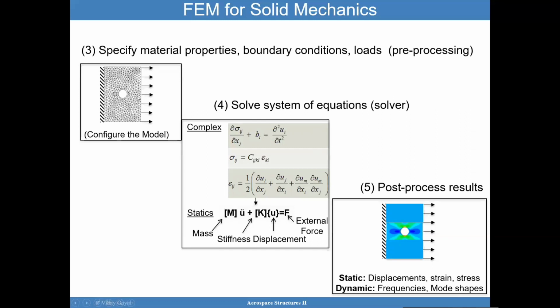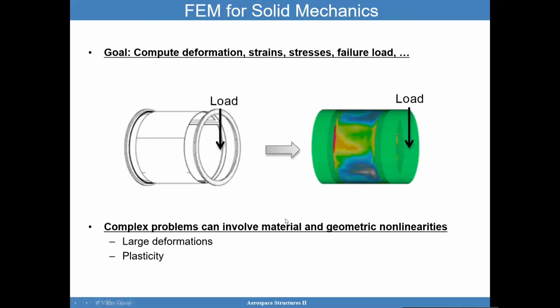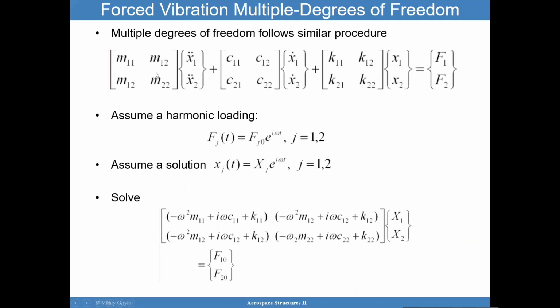I've taken a continuous system, discretized it, and now have a mass matrix that represents the system fully. I have the acceleration term, which represents the deflections of the system. And then I have the stiffness matrix, which represents the stiffness of the system, multiplied by the deflection, and this is equal to force. If you notice, this looks a lot like the equation that we had here, which is 2 by 2: mass times acceleration plus stiffness times deflections equals forcing function.